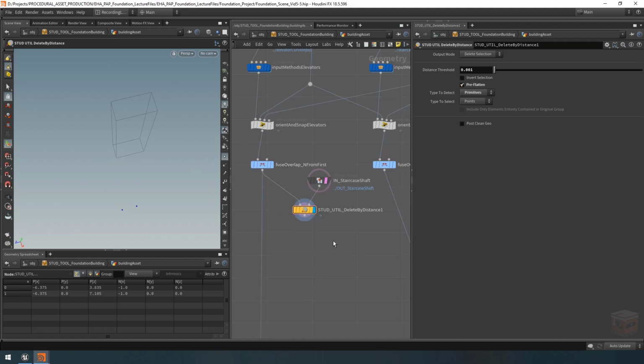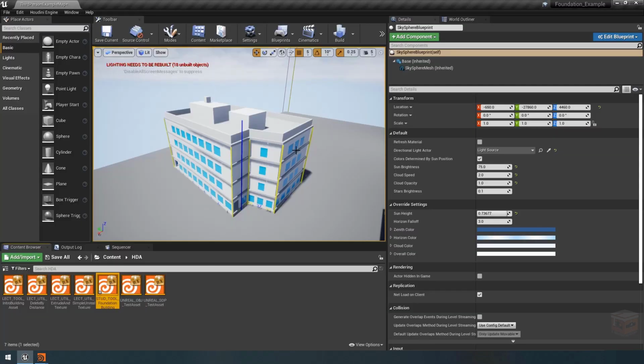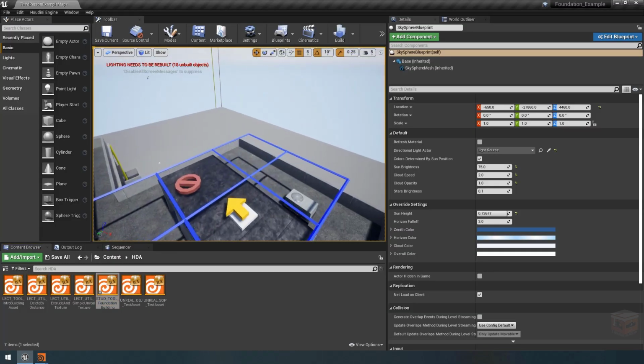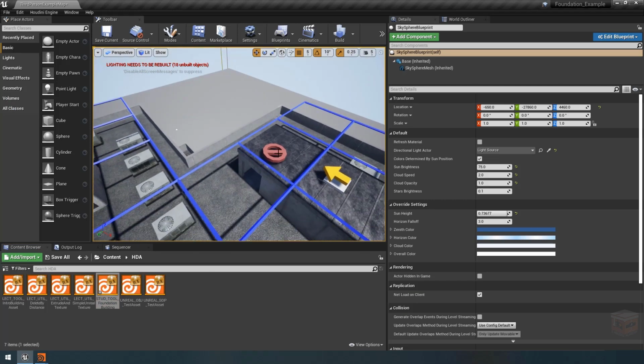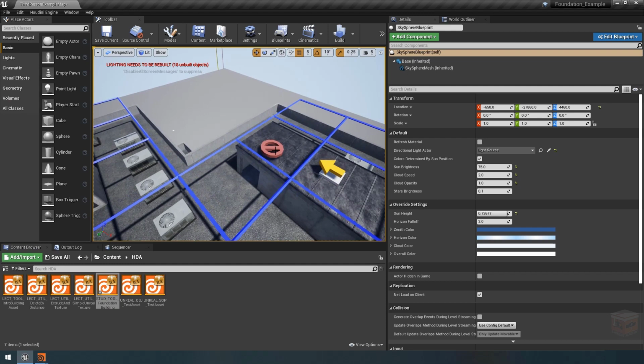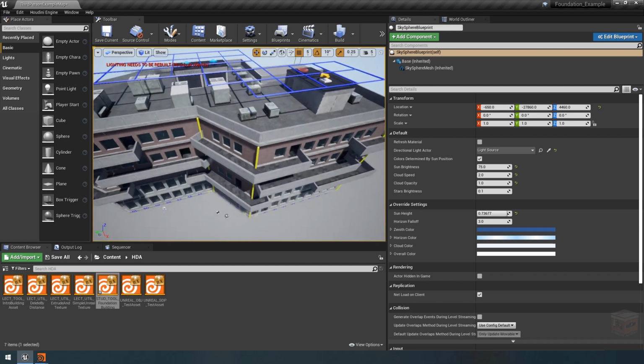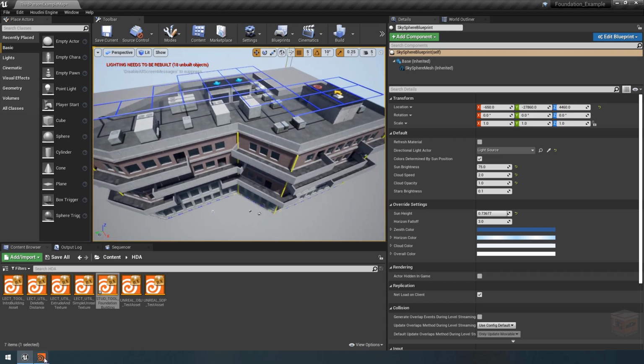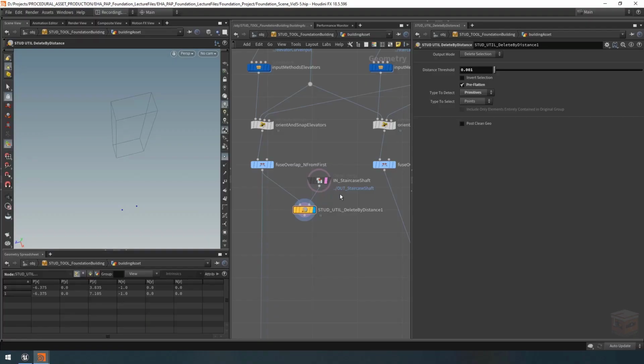But I don't really want to remove the point because I do want to provide a visual element on our tool that indicates that we have actually overlapped an elevator with our staircase. And for that, if I remove the point, we will never get to see this. So instead of actually deleting the point, let's go ahead and simply group it. And then we can filter it out later instead.